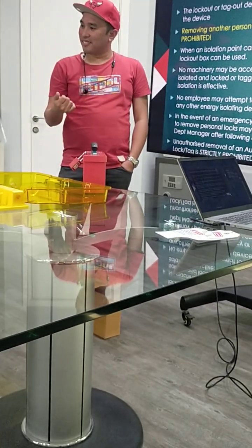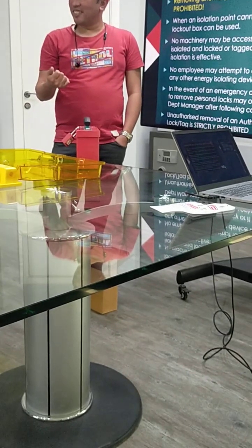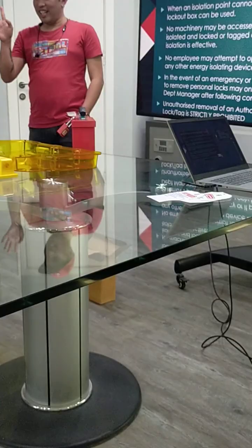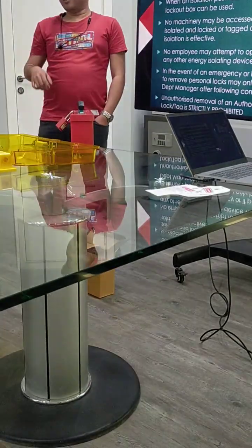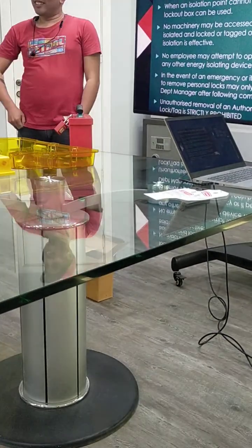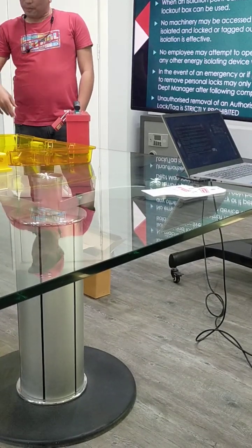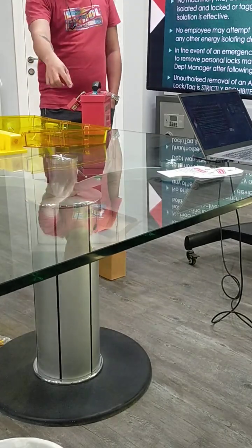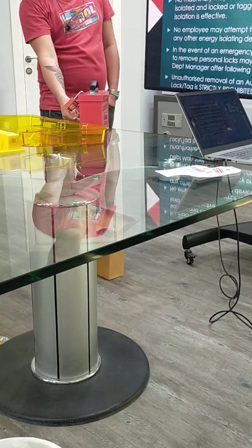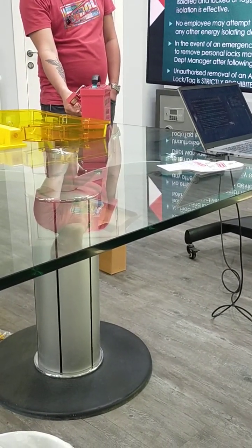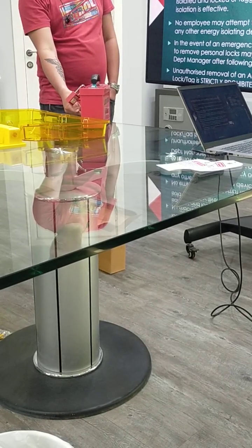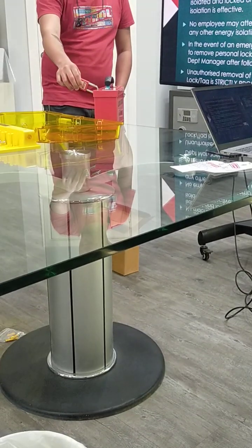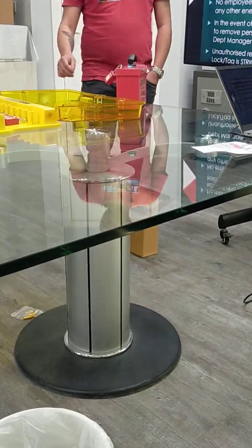Because, for example, Assis is the engineer, so he will padlock this one. This one is the mechanic, so he will padlock it. Then at 4 o'clock is his off. He will take up his padlock, but this one is still working. No problem, because the key is still there inside. There is no more padlock there, but Assis's padlock is still there, and this one is also his own padlock for the mechanic.